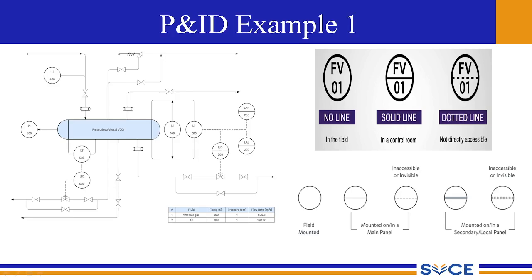So you can also look at the various symbols provided in the previous lectures and try to understand a few other symbols that are not explained to you. I leave it to you as an exercise so that it is interesting for you to comprehend the various P&IDs. So what is the meaning of this dotted line? It represents an electrical signal to the actuator.